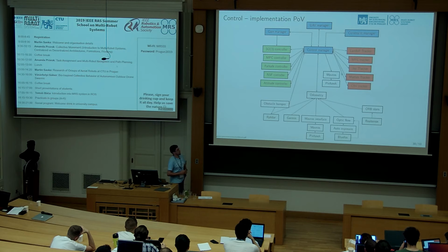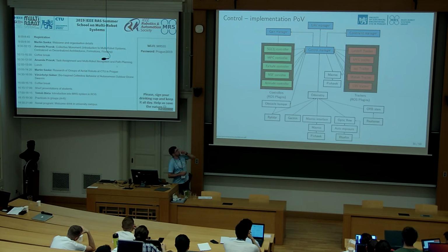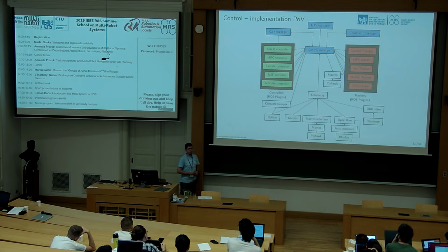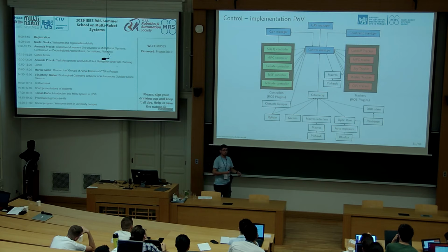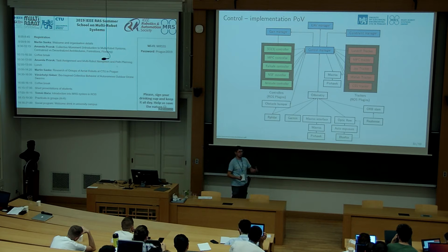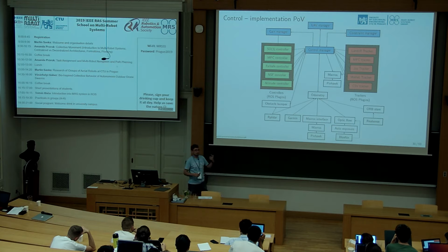So the pipeline altogether looks like this. We have also some other managers. For example, the gain manager is a manager which manages, that's a terrible word, gains for the SO3 controller. It's very important to be able to switch control gains. Those are the numbers that make the controller stable, and we switch the gains on the fly based again on the type of flight which we are doing. Like we need aggressive maneuvers, but they don't need to be precise: switch to lower, softer gains. We need slow flight, but very precise: we can switch to tighter gains, higher numbers.